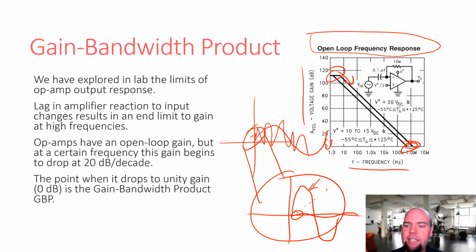So you can just read it. Looking at this data sheet, we have 2 lines here, which is probably the range of values. It looks like it's about maybe 900 kilohertz based on looking at this. We might be able to see it a little better here. At 1 kilohertz, we're about dead center between that range. And what's the gain here? The gain is 60 dB. Well, what's 60 dB? That's 10 to the power of 3. That's 1,000.